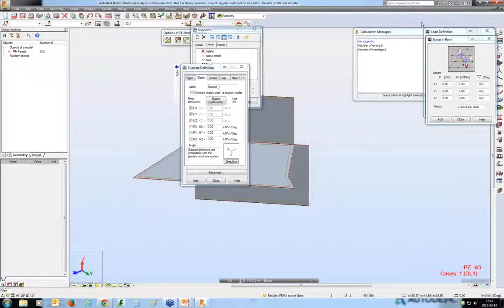Okay, so we still have a few more questions that are being answered. Again, maybe slightly off topic, but I'll read through those. Now that everybody's got the chat window, they'll be able to send us more questions. One that came in earlier that Guillaume answered: I want the panel to update when I move the geometry of my nodes manually. And the response is, when you manually move mesh nodes, mind that you merge the nodes with the structure correction tools as shown in the presentation, then freeze the mesh and run the model generation.